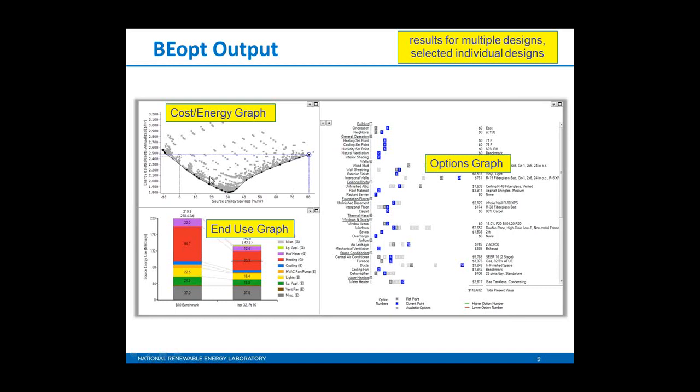This, as I said, was an optimization. Each of these points represents a combination of different efficiency measures. From a purely economic point of view, based on the building that we simulated and the components that we made available to the optimization, down here, these points here would be your most economic, sort of globally economic building designs. And generally speaking, these are efficiency designs, and then at some point, you would start to put PV on your house when it becomes the cheaper option.